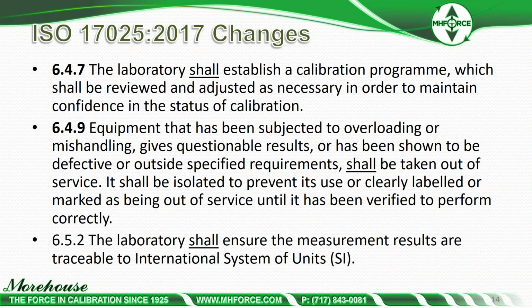6.4.9: equipment that has been subjected to overloading or mishandling, gives questionable results, or has been shown to be defective or outside specified requirements shall be taken out of service. It shall be isolated to prevent its use or clearly labeled or marked as being out of service until it has been verified to perform correctly. ASTM E74, which is a force standard, has a section saying if it's overloaded, it needs to be recalibrated. This is essentially saying the same thing. It's good measurement practice, if you think something has been overloaded or mistreated, to take it out of service immediately until you have it checked and verified.